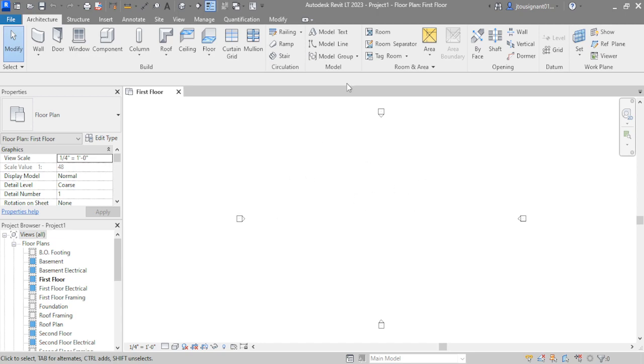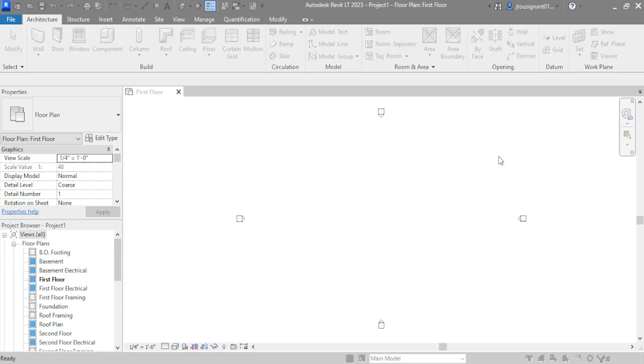The first thing I do when I am opening up a project, once I've picked the template that I want, is go into File, Save As Options, and save this so that I can begin making the file, because you don't want to save over the template that you have in the original file. Especially if you open this up based off your template, you don't want to save it over the same name as well. And if you start a template from Revit, it's always going to call itself Project 1.